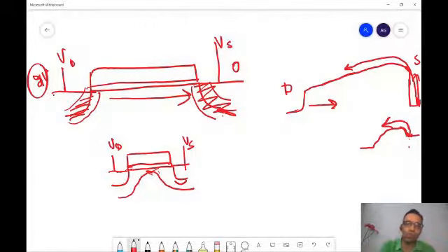Whatever junction forms, there will be some depletion width formed, and then we have this voltage applied, due to which this depletion would have changed already. Yes, we're talking about a static condition. Okay, so we are not in, okay. I thought that if we increase VD, maybe we can achieve DIBL in long channel also.